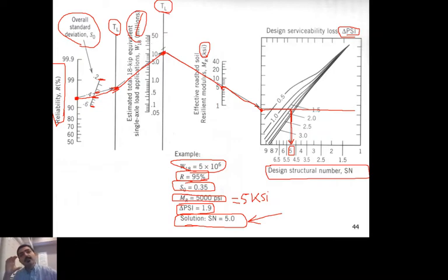If you're designing the top layer, once you get to this stage here, the E, you need to use the layer underneath it because now you're designing. Let's say I'm going to design a hot mix asphalt layer. The hot mix asphalt layer will have to protect what's underneath it. That's why I'm going to put the E2 of the road bed, the effective road bed soil resilient modulus.